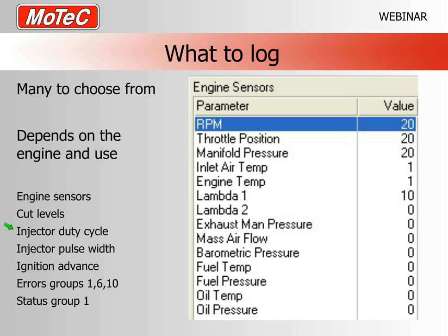This will let us know, while you're tuning or at any time, if the injector duty is going to run out. Anything greater than 90% would give me cause for concern. So certainly tune related log sets would want that channel.